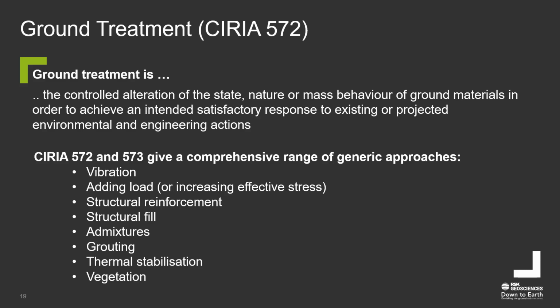If we add load to the ground in some way, then that load will make the granular deposit settle. It might not be an efficient way of doing it, but it is a way of doing it. So if you've got enough time to wait, you can put a surcharge embankment in place, and it will generate settlement over a relatively short period of time if it's granular. But if it's clay material, then it would be over a longer period of time.